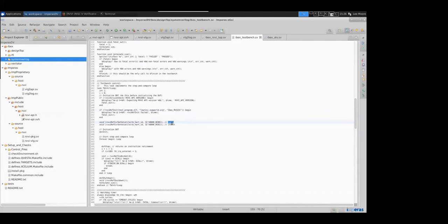Because if you imagine you have a piece of code that executes a branch on the value inside of one of these volatile registers, then you have to ensure that that branch takes the correct flow of control based upon the value in that volatile register. So there are some things we do to ensure that registers marked as volatile are passed across from the RTL to the reference model to ensure that execution of programs remains consistent in both of those domains.